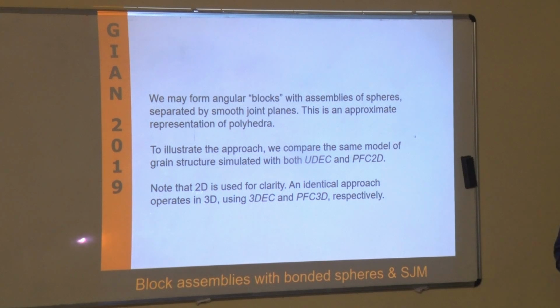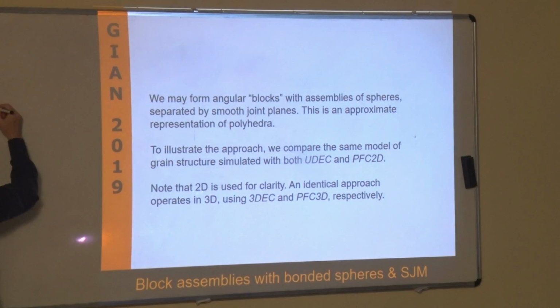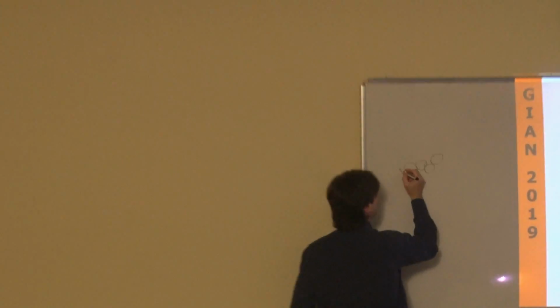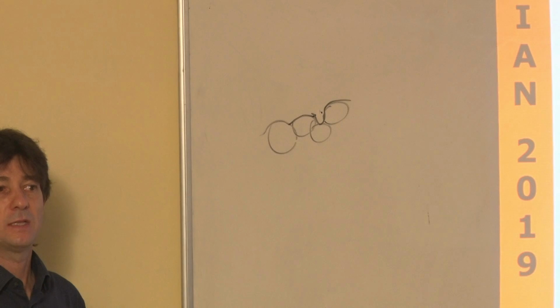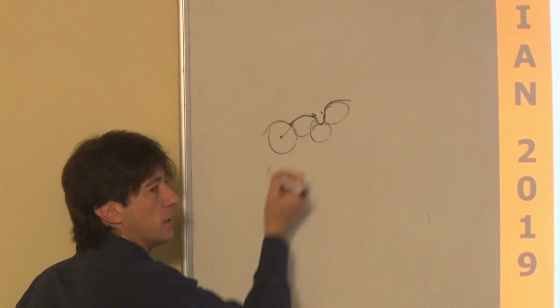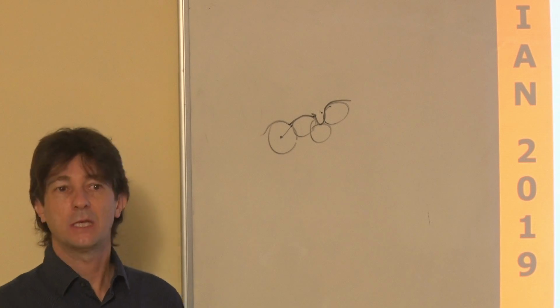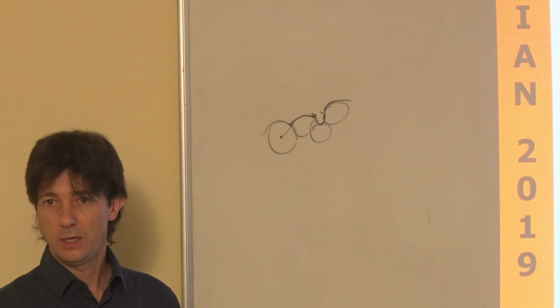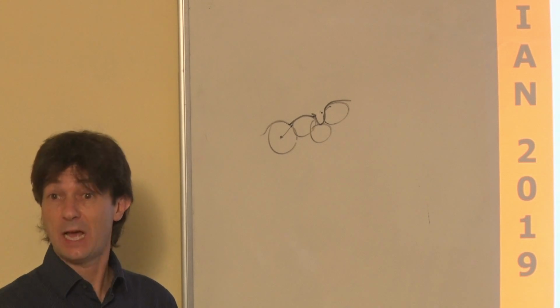The other problem that PFC and all the particle flow, particle element codes have is that when you have a fracture and you break the particles, if this is your surface, you have quite an inherent roughness that is a function of the radius of your particles and the packing. And sometimes it is not really reasonable, it adds interlocking that is not there at the scale you're modeling.